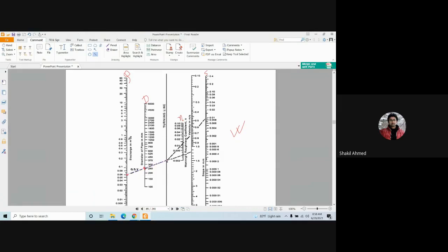Now here you need to change your direction based on n. What is your n? Your n is 0.014 here. So rather than going this direction, you will move your direction based on your n. Are you following me? Yes, sir. If your n is 0.02, you will be here. If your n equals 0.006, you will be here. If your n equals 0.01, you will be here. In this case your n equals 0.014, so you just extend it accordingly,